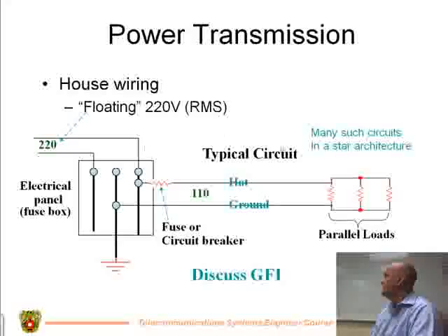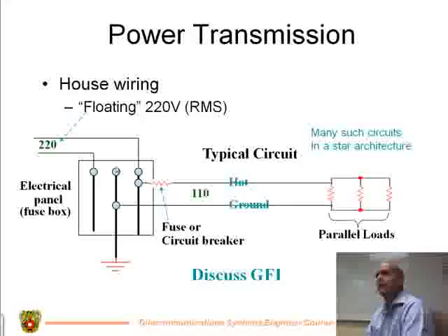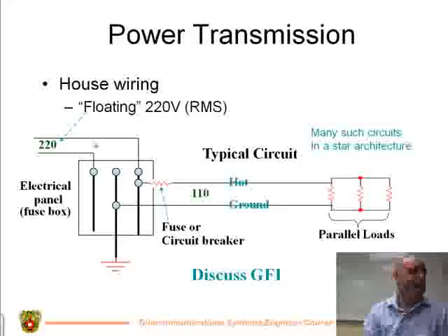Then you do a bunch of these in a star architecture because every breaker has its own circuit like this, right? And then all your loads are just in parallel. So what happens when your kids start going around the house and plugging something into every outlet? You're dropping the impedance. Yeah. There we go. Anyway. Okay, so now what is GFI or GFCI?